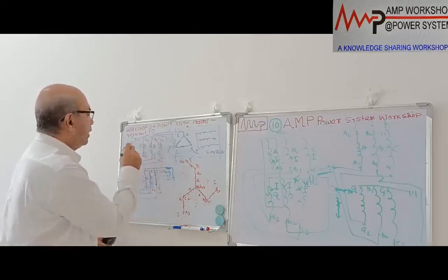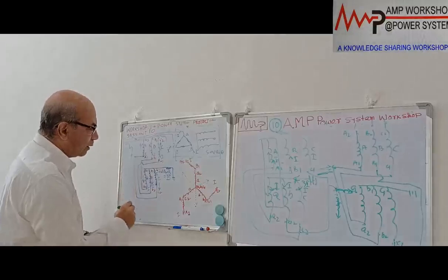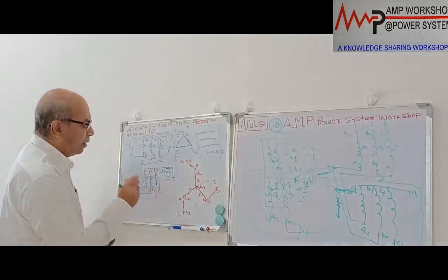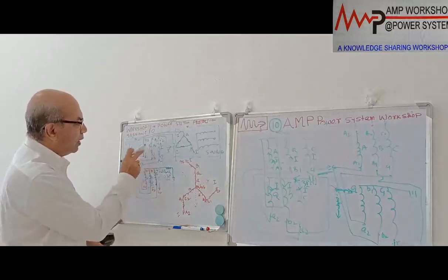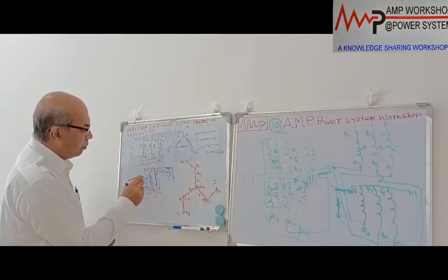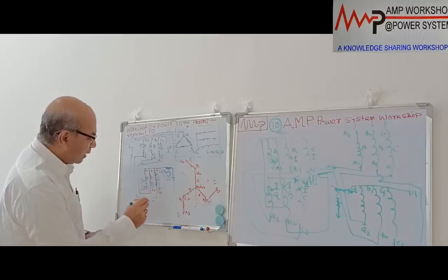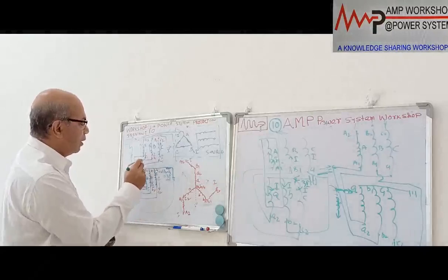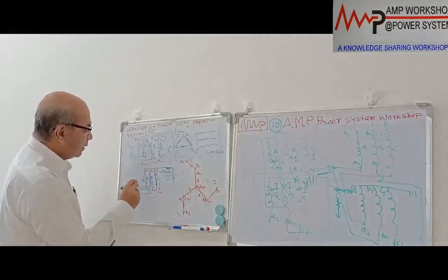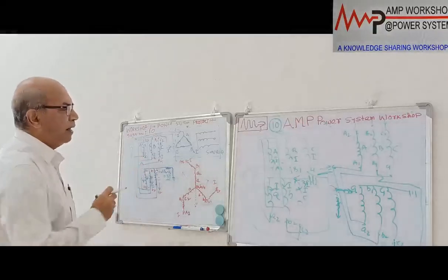When there is any earth fault anywhere, immediately the earth fault current will come through the ground, and then it will come over here. 3I will be coming, because all the windings are equal in impedance value, so equally the current will be distributed, I. This current is going this way and then it is flowing this way. So when you look into the A phase, this current is this way, this current is this way, so they are balancing each other.